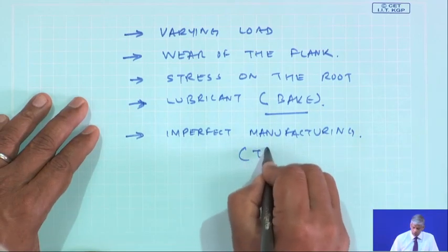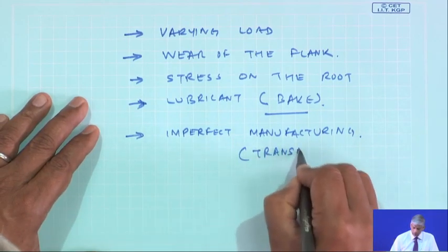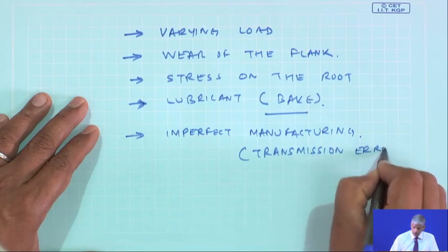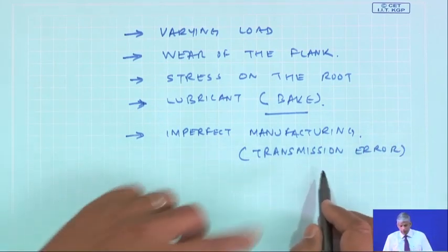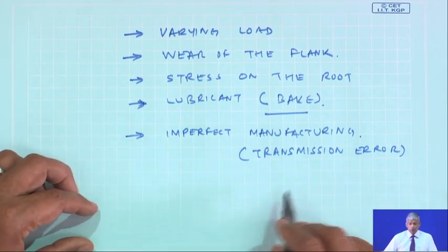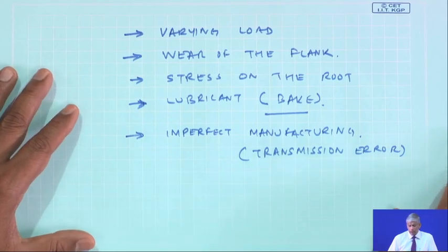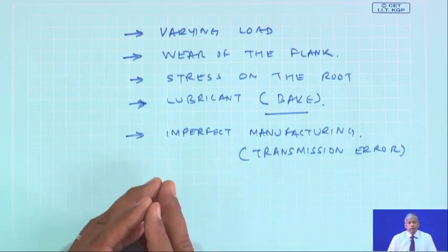In terms of the transmission error, that means there are radial clearances in the bearings which are supporting the gears meshing against each other. So, all these conditions happen, and in the normal operation of a gear these get complicated and so on.